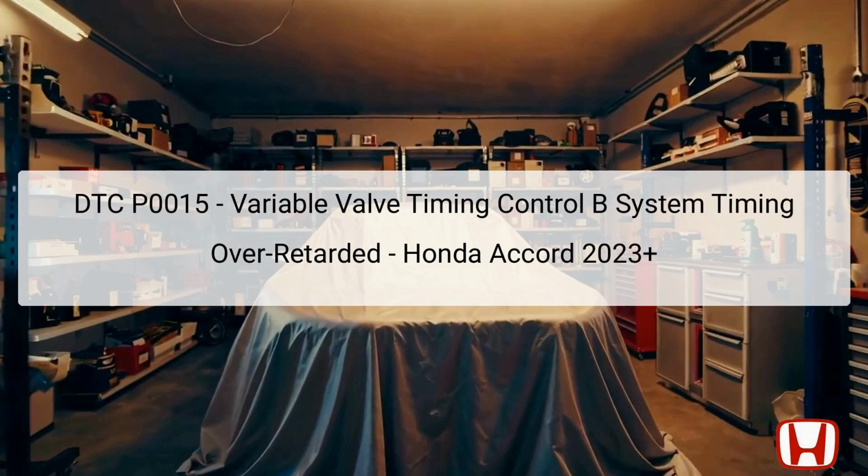DTC P0015 refers to the Variable Valve Timing Control (VTC) system encountering a timing issue where the exhaust camshaft phase angle is more retarded than what is commanded by the Powertrain Control Module (PCM). This inconsistency triggers the PCM to identify an abnormal condition, resulting in the storage of this diagnostic trouble code, DTC. The VTC system is crucial for optimizing engine performance and efficiency by adjusting the timing of the intake and exhaust valves based on various driving conditions.